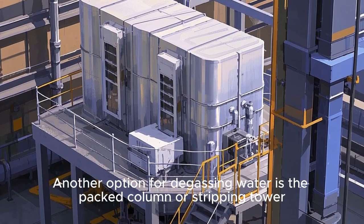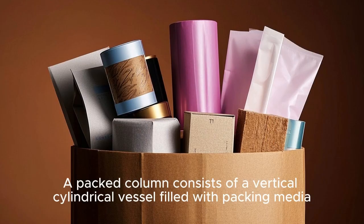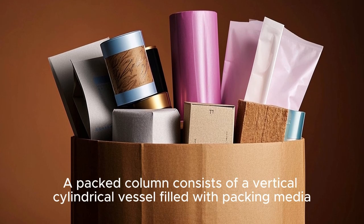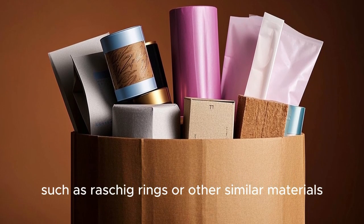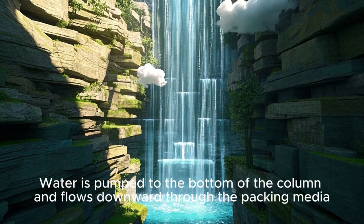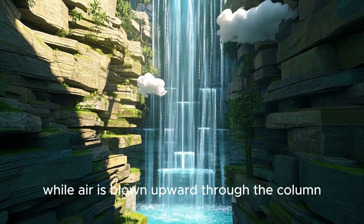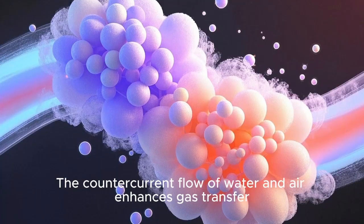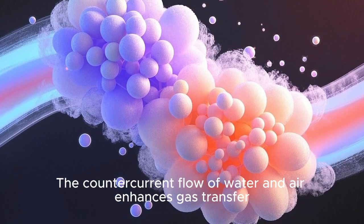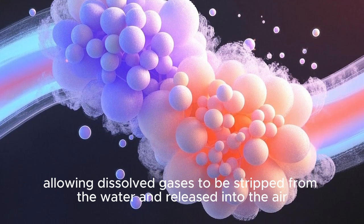Another option for degassing water is the packed column or stripping tower. A packed column consists of a vertical cylindrical vessel filled with packing media such as Raschig rings or other similar materials. Water is pumped to the bottom of the column and flows downward through the packing media while air is blown upward through the column. The countercurrent flow of water and air enhances gas transfer, allowing dissolved gases to be stripped from the water and released into the air.